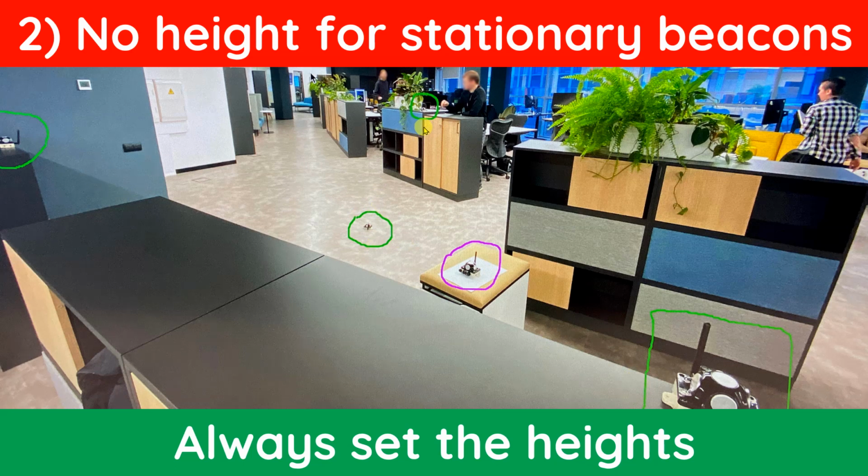So if you do not provide the height for the stationary beacon, then the system even theoretically cannot build the map and cannot measure the position, because it can measure the position of the mobile beacon against the stationary beacons, but then the stationary beacons must be against something. What is this something? This something is typically a floor, as we call it. So for this beacon it must be 0, for this must be some height set. Okay, so each stationary beacon must have the height set.